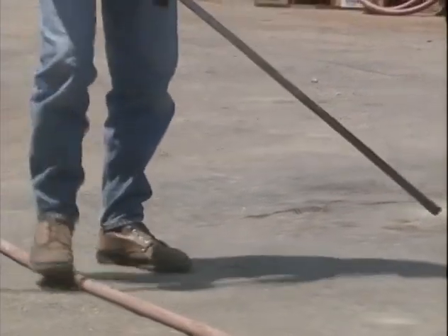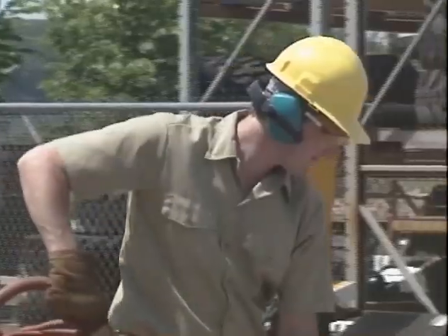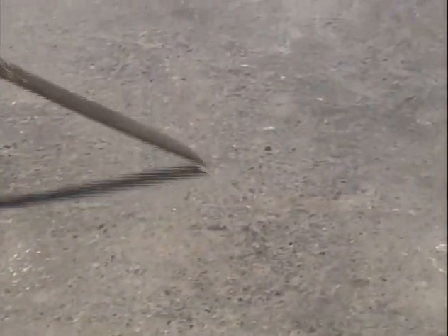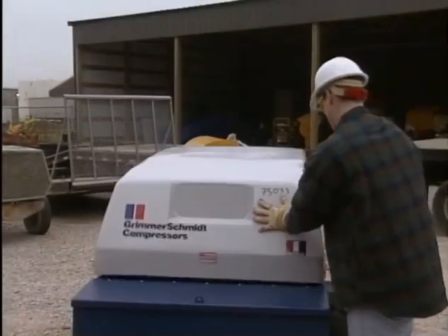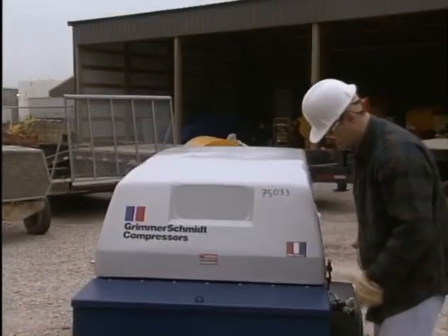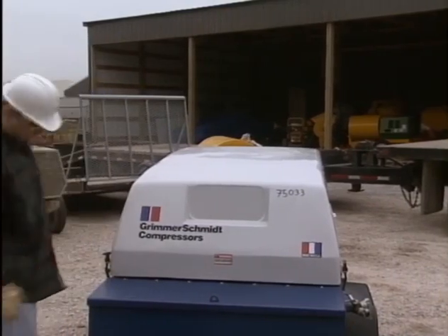Make certain all personnel in the area are wearing appropriate personal safety equipment. Do not use compressed air for breathing. Do not direct it at yourself or other persons for any reason. Do not allow compressed air to blow on foodstuffs. Make certain that compartment doors, guards, and panels are secured to prevent dropping on personnel.